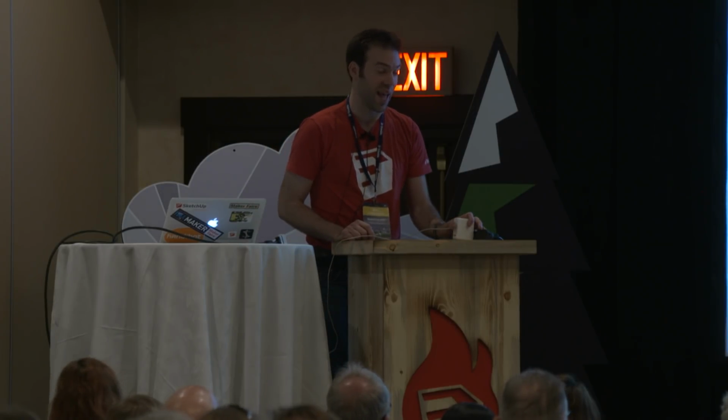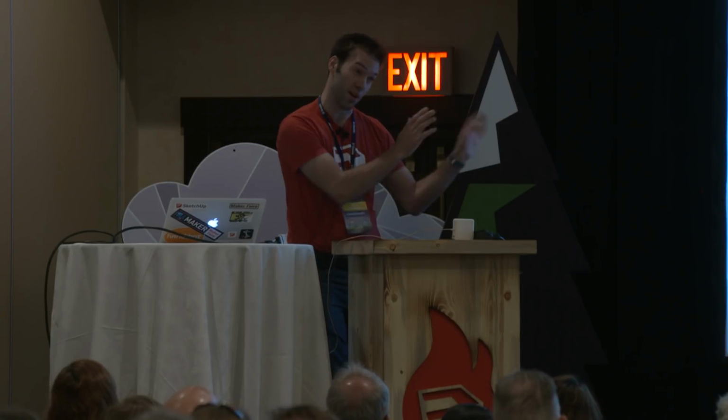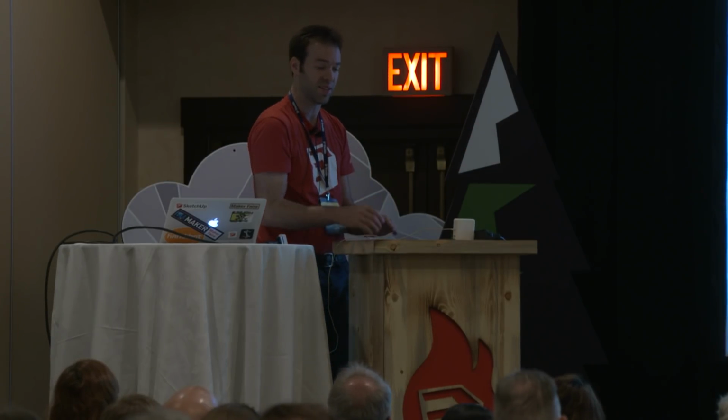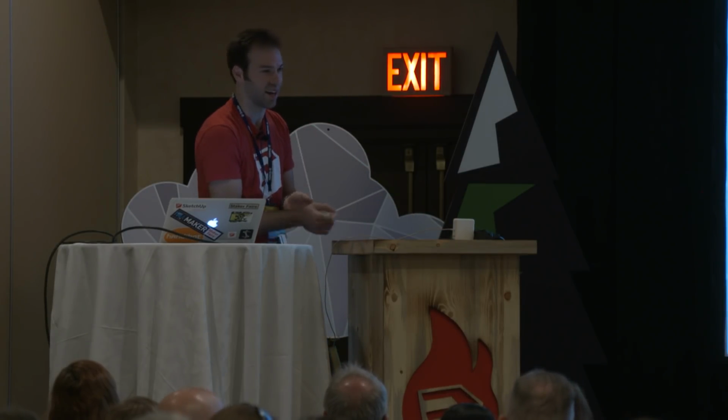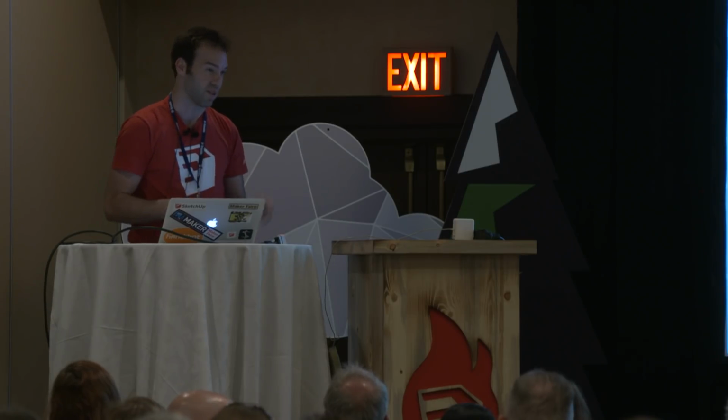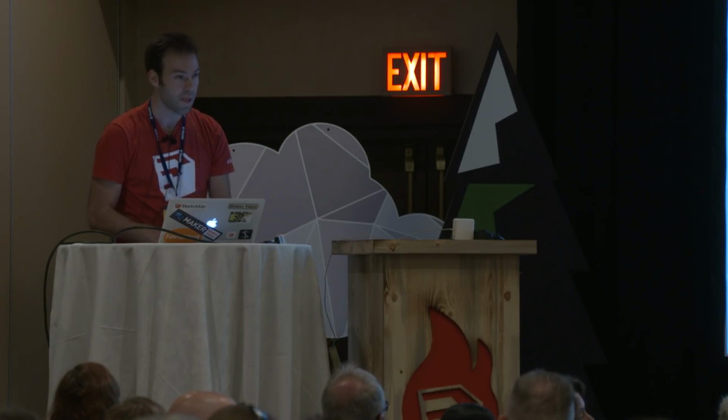And we're going to get to this. I don't do layers until the end when I'm nearly done. The only thing I typically use layers for in an interior model like this is I'll put cabinetry and furniture on a layer. I'll put tchotchkes, little things that don't really matter but might slow me down if I'm modeling, but I want in a picture, on a little tchotchkes layer. And they're really easy to set up after, so we'll do that towards the end.